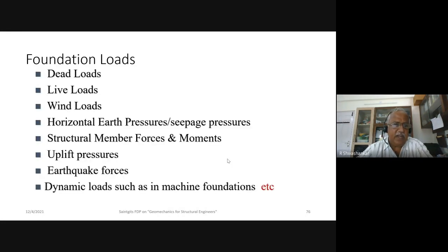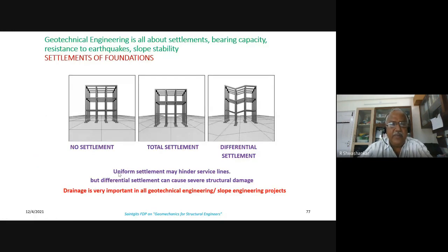We consider different loads, and normally for tall structures, the lateral loads are more critical, that is wind loads and earthquake forces. We consider either the worst wind load or the worst earthquake. We don't consider both of them to occur at the same time.